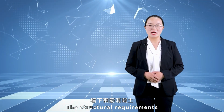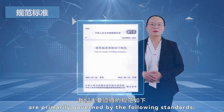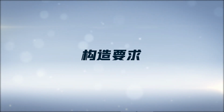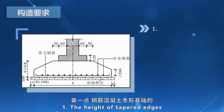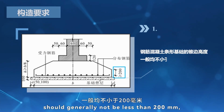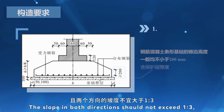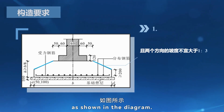The structural requirements of reinforced concrete strip foundations under walls are primarily governed by the following standards. The main construction requirements are as follows. 1. The height of tapered edges of the strip foundation should generally not be less than 200 mm, including the protective layer. The slope in both directions should not exceed 1 to 3, as shown in the diagram.